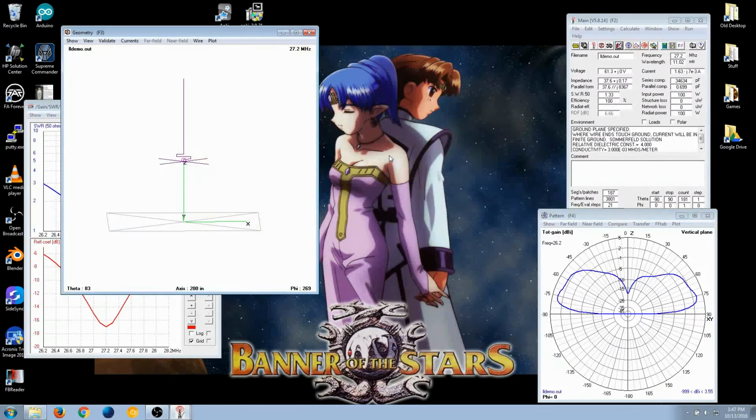But like I said before, regarding the auto segmentation that you were concerned about, it says one segment, but when you look at the model, the actual segments on the model that gets run, it's not one segment. It's whatever the auto segmentation was set to. To give you the exact number so you can enter them into EasyNEC, I'd actually have to go through and count them.